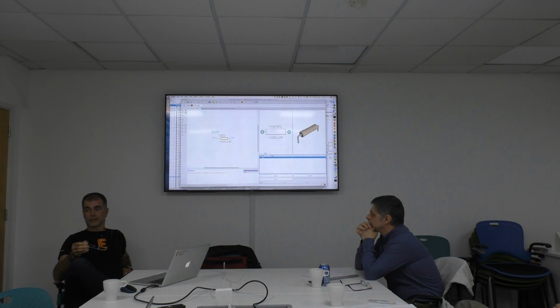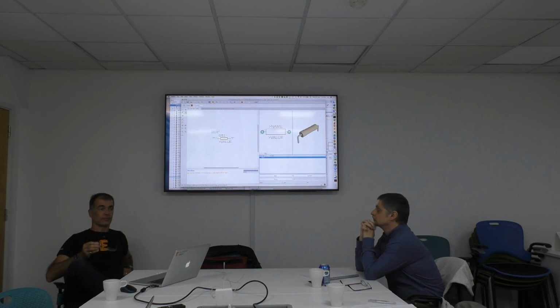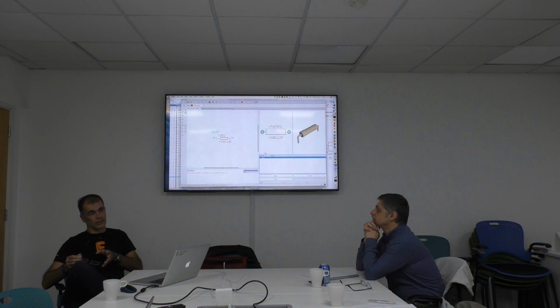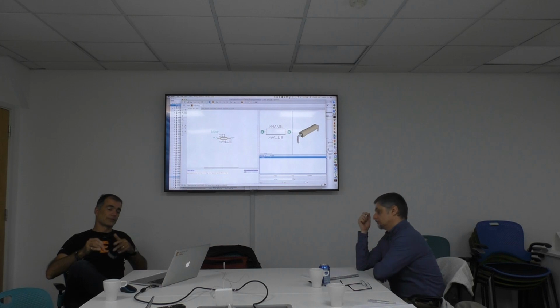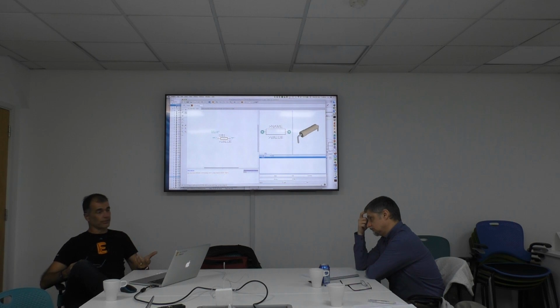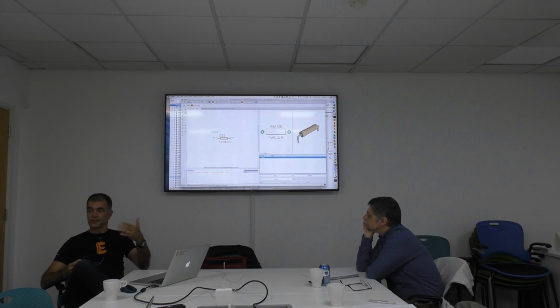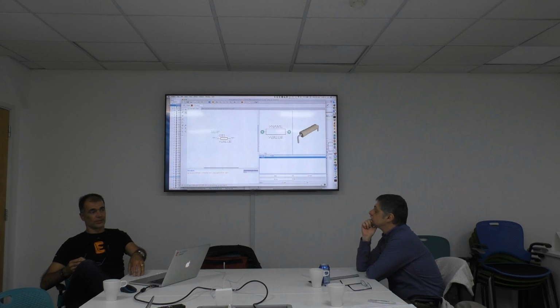This would typically be the case if you have an LM555, because the LM555, that's the value of the thing, and the device name is the value. Usually, if you set it off, that is the case. If you set the value on, this means it's user definable, for the resistor as we have it in our libraries. You get the resistor, it's named R1, but you have to decide the value. Is it 1 kilo ohm or 10 kilo ohm? So that's what I can see.